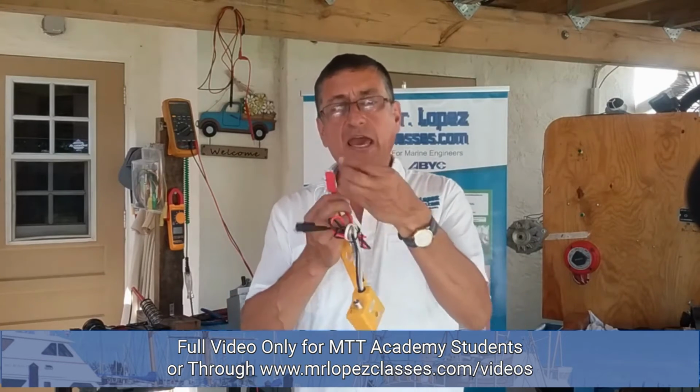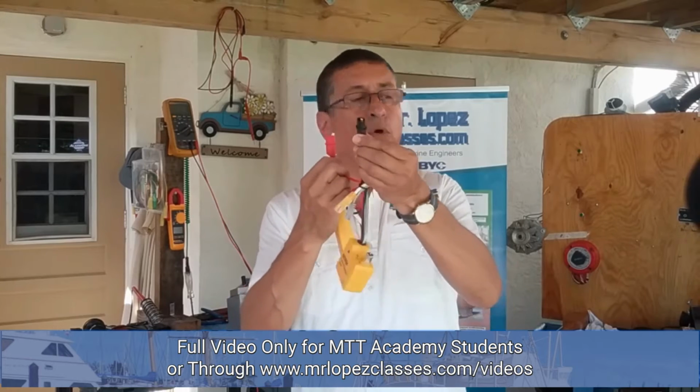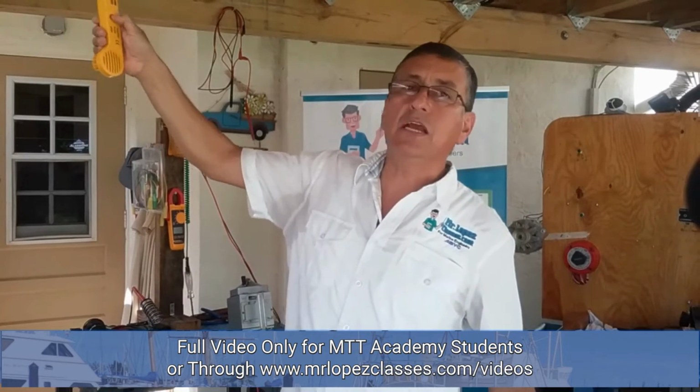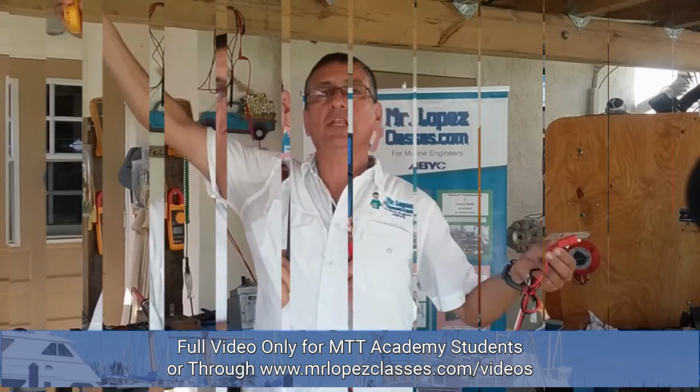With this equipment you connect one end, the black end, to any ground, and this one to the beginning of the cable. And you start this one and you follow the cable. When the intensity and the light increase here, this is the cable, this is orange, this is exactly the cable that you need.